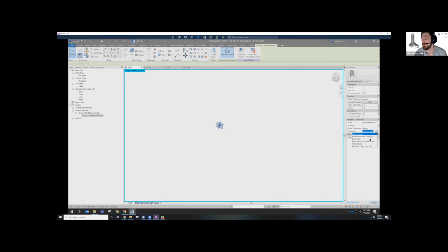So there's a number of ways you can actually place adaptive panels within Revit. We tend to use Dynamo and Rhino.Inside, which actually means there isn't a host. The host is the Dynamo script itself, which becomes irrelevant. You can use massing faces, divide massing faces, and then place adaptive panels that way. And then global is just the file itself. So X, Y, and Z of your global environment. Using Dynamo and Rhino.Inside, it tends to skew these ideas of instance, host, and global, because when it's placing the point, it's as if you're going around and clicking rather than locating it on a surface or something like that.